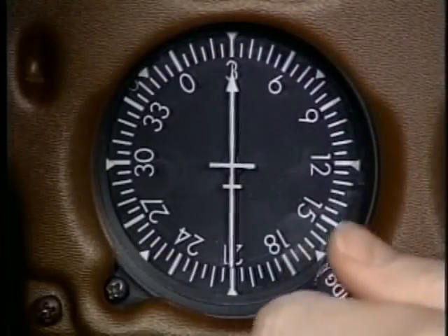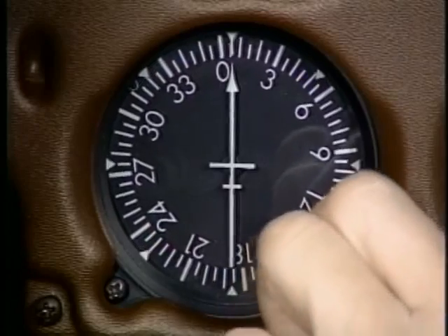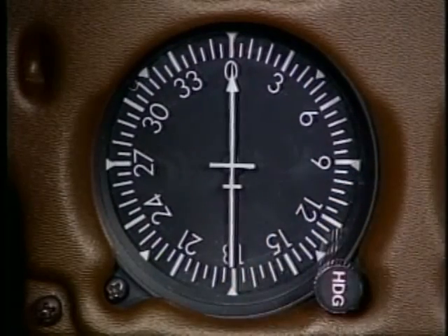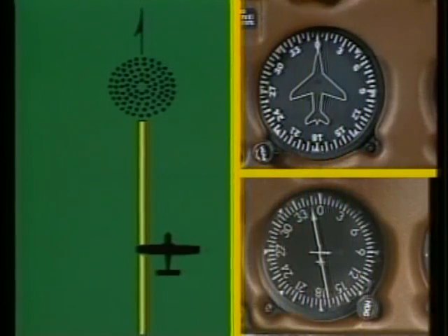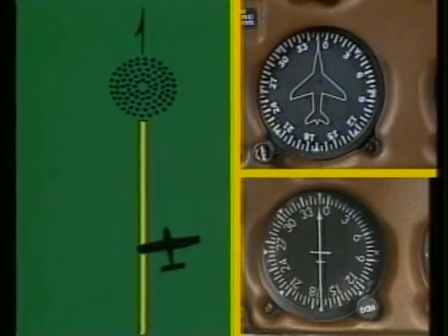Since the ADF does not automatically provide a wind correction angle as a VOR does, let's review the bracketing procedures. In this example, you've drifted right of the 360-degree bearing to the station. The ADF is sensing a crosswind by pointing to 350. To regain the course, you apply a 10-degree correction into the wind and reset the ADF to match your heading. If your heading and relative bearing remain constant, you've corrected for the drift, but you will not intercept the 360-degree bearing.